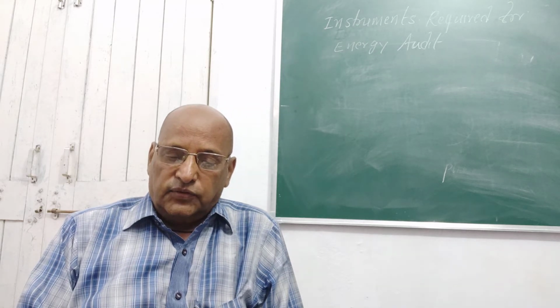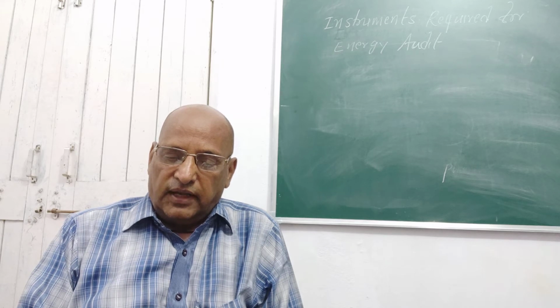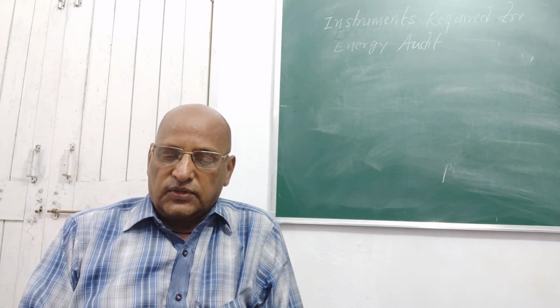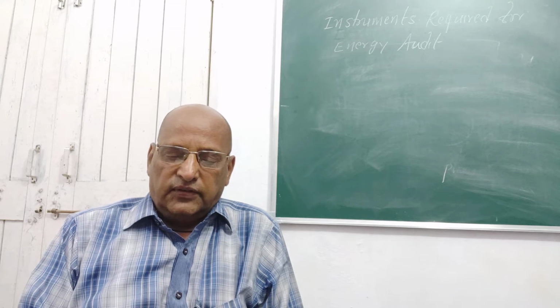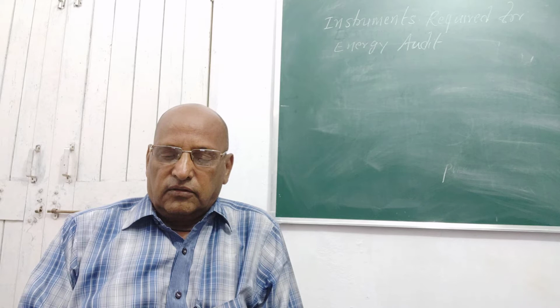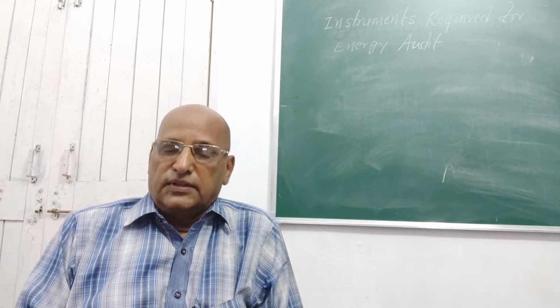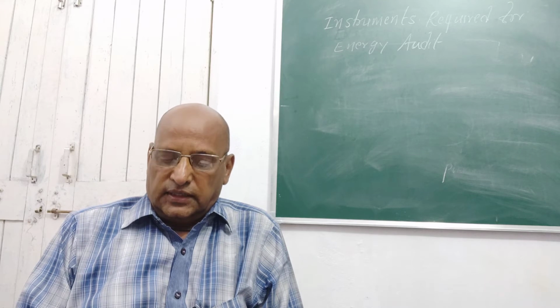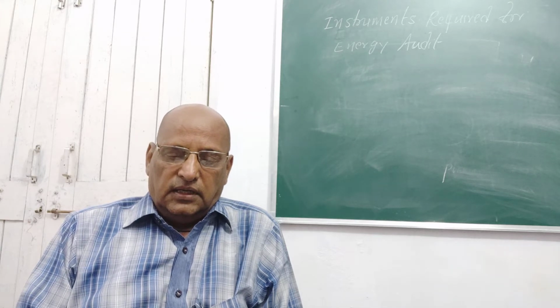Then third is the fuel efficiency monitor. The values of common or standard fuels are fed into the microprocessor, and this instrument measures the flue gas temperature and oxygen content, and calculates the combustion efficiency. So this is the fuel efficiency monitor, the third item.